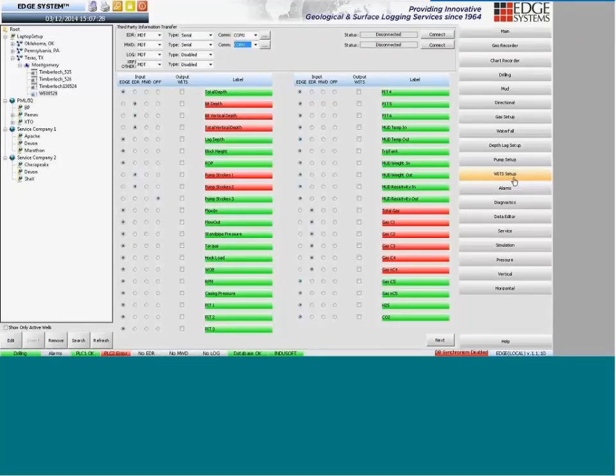And at the very top, you can see we can acquire data from the rig control system, the measurement while drilling folks. We can export out to various third-party logs if we need to, and we can acquire data from miscellaneous equipment. In this case, it's labeled XRF, which is a type of analyzer that looks at the individual rock properties in terms of elements and analyzes the data from there.